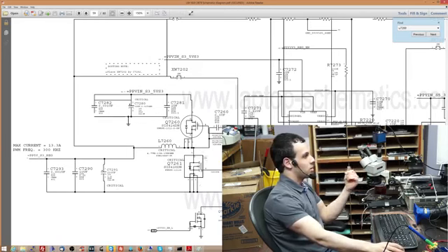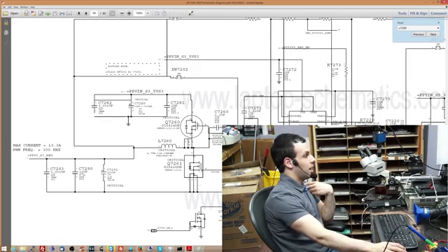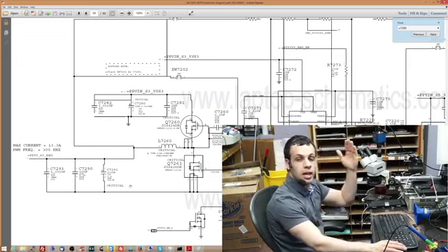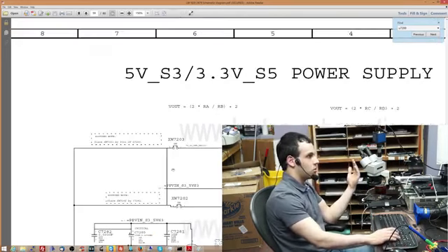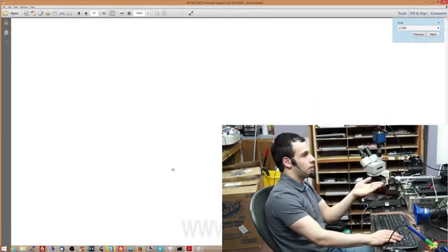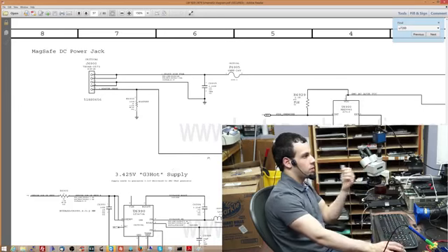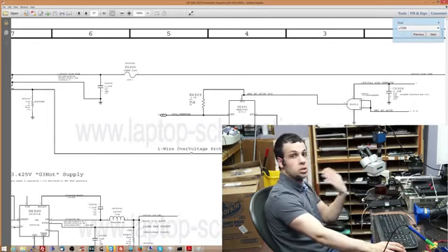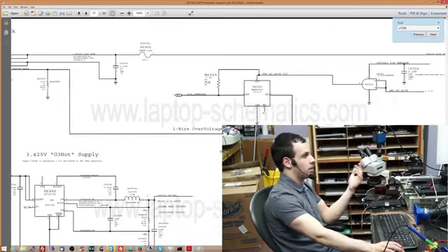That's how you read a schematic. So you see 2 transistors being controlled by a controller chip, and then right where the output of that top transistor is, you see an inductor, and then you see a bunch of smoothing capacitors. That is a buck converter. Again, you should know what these things are after you have some experience, after you go to the basic lessons.